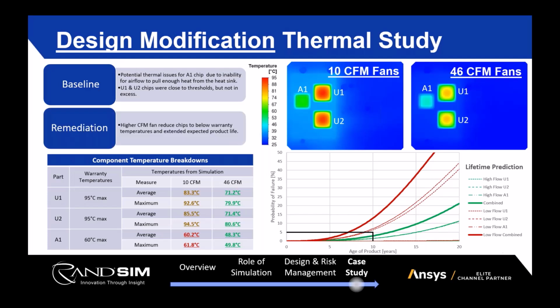And this was all through just integration of that higher CFM fan, which is a fairly easy substitution to do in the simulation. So I was able to quickly get through this and now move forward with confidence that from a thermal perspective and from a solder fatigue reliability perspective, I was going to meet the product needs and not have to worry about any warranty claims for that reason.